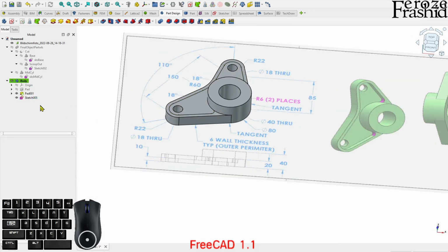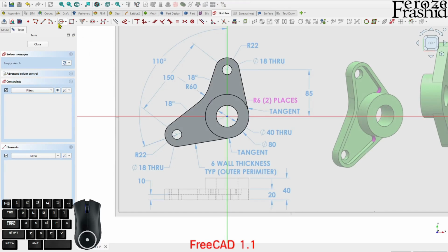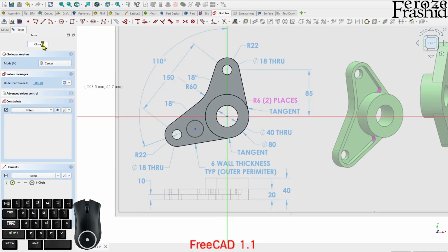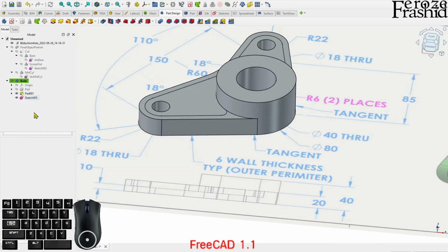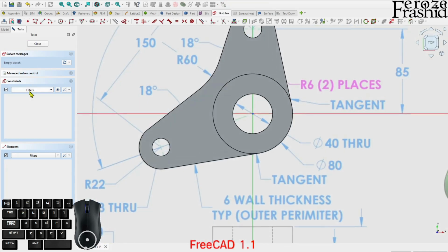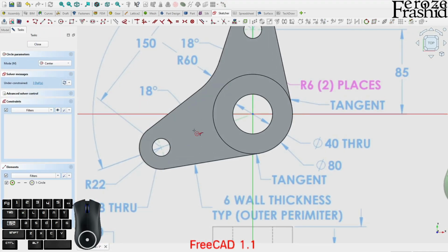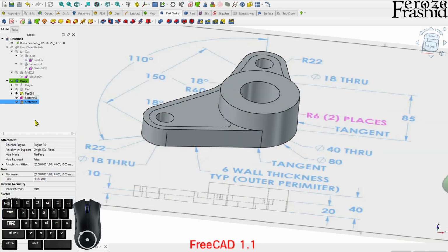Now if you are going to create a new sketch on top of this face in PartDesign, you can select it and create sketch. So use this sketcher button, and it will make the sketch right on that face, which we said we would not advise doing. If you don't do that, to avoid this TNP, and create a new sketch altogether without selecting anything, it will ask you which sketch plane you want to build on, and you can choose this XY plane right in here and draw something. So this actually did not give us the offset to begin with, but we can still offset it.